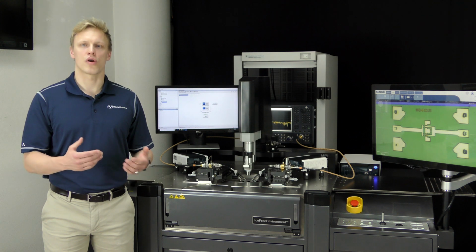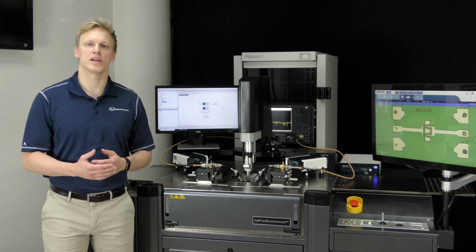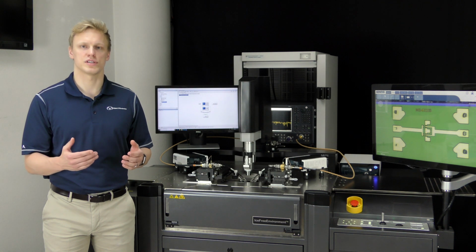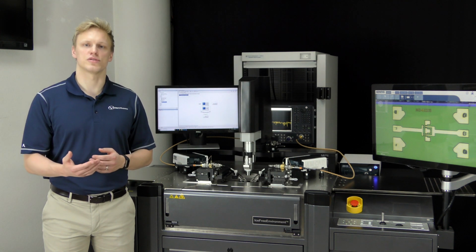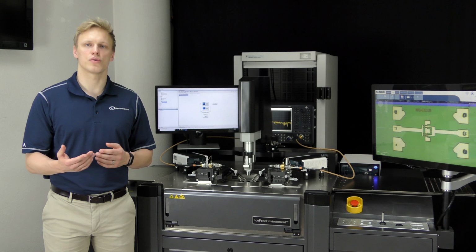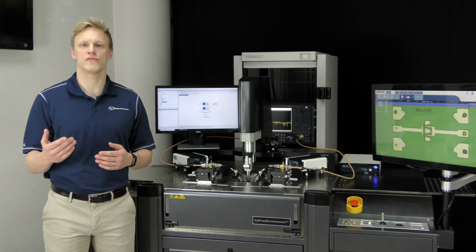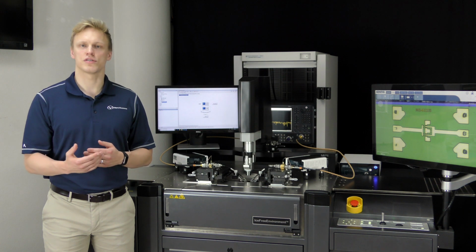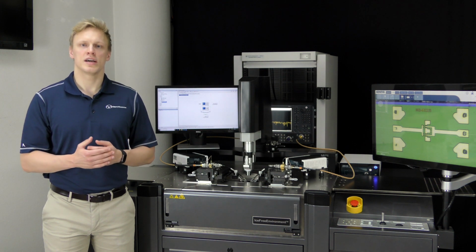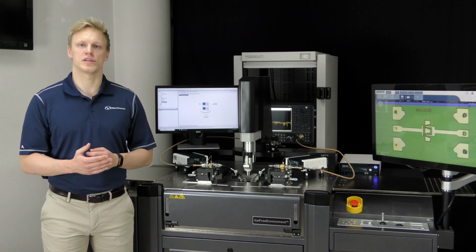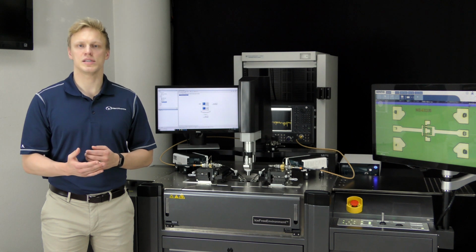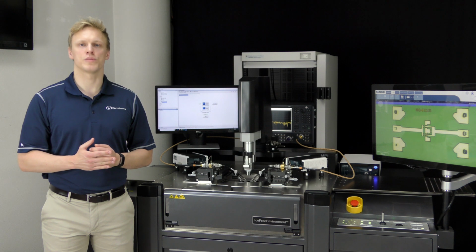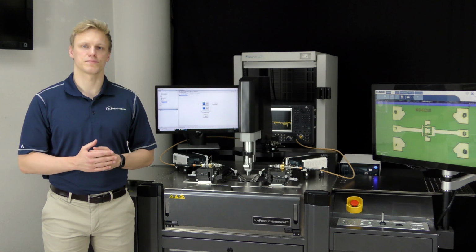Current and voltage, or IV measurements, are used to describe the relationship between a transistor's input and output currents and voltages. For a typical field effect transistor, this is usually shown as drain current versus drain voltage for a set of applied gate voltages. With modern technologies, such as gallium nitride, it's not enough to simply measure a transistor's performance under DC bias conditions, but rather, we need to measure the performance under pulse bias.